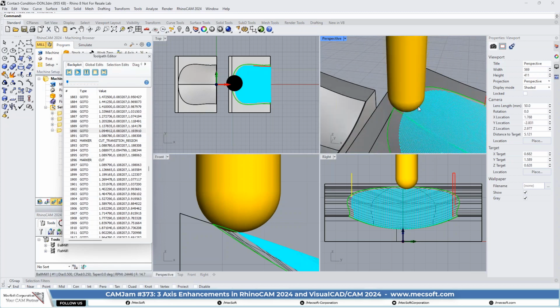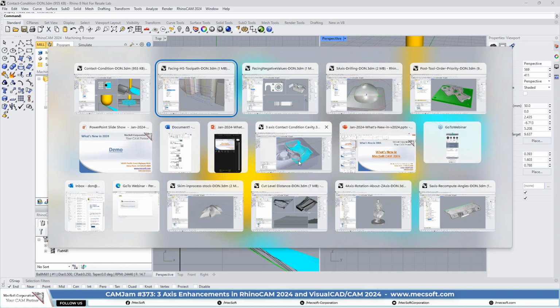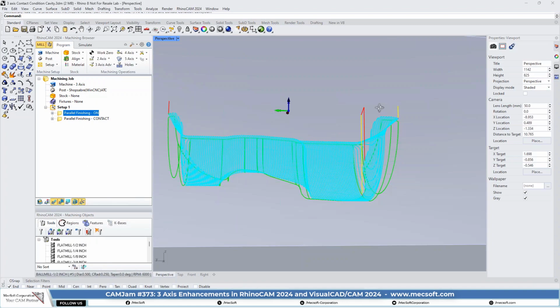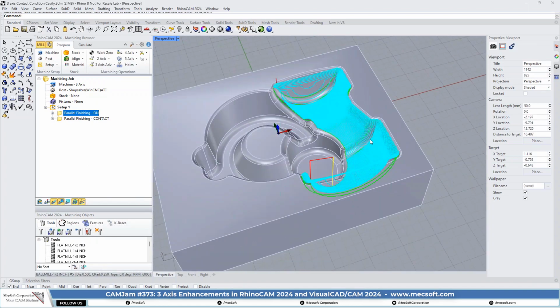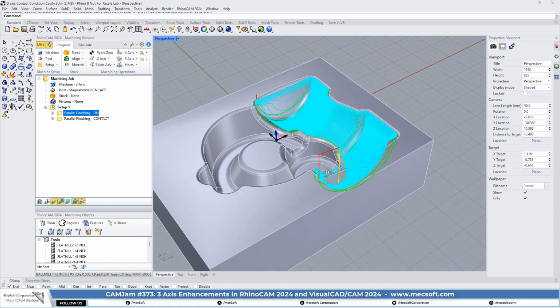The path is only calculated based on the tip of the tool, but that entire cavity is being machined very precisely and not going over that parting line back and forth as it was in the on condition. Now, we also have another part lined up for this, which shows this as well. You may have seen this mold cavity. We use that in a lot of different cases to show different things.